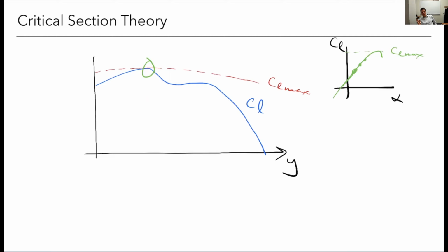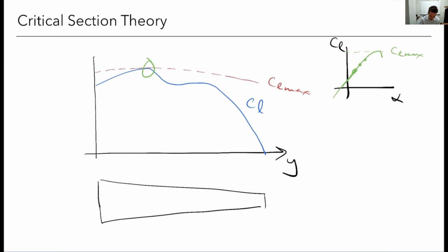This is an approximation. It's not exact because what this assumes, let me draw this wing here. So here's like the wing shape, okay? What this assumes is that the streamline over every part of the wing is perfectly parallel to the free stream. And so it acts like a bunch of 2D airfoils and they're independent, but that's not true.